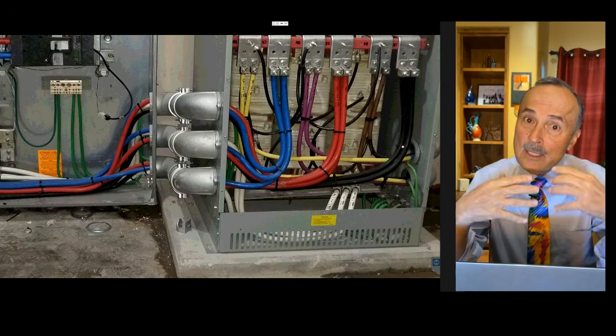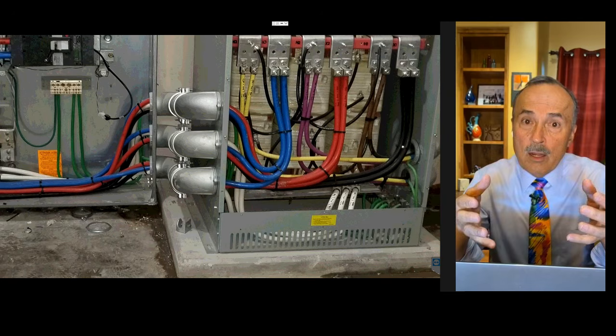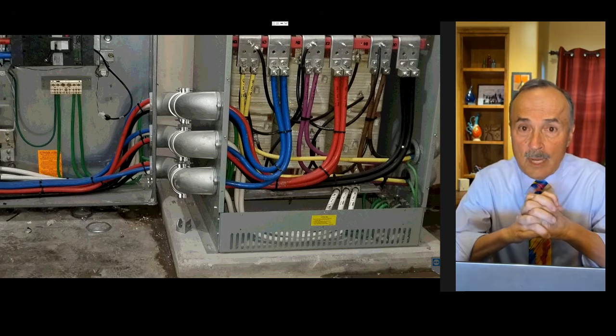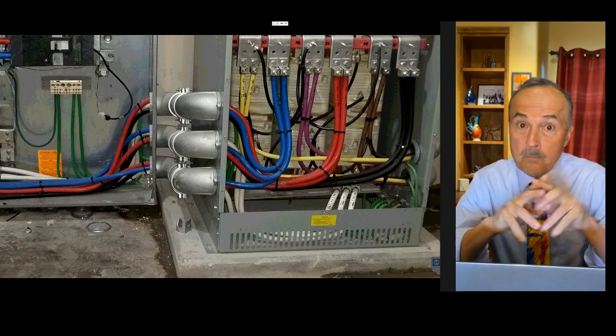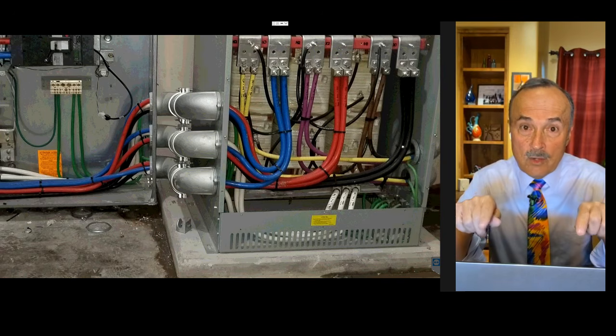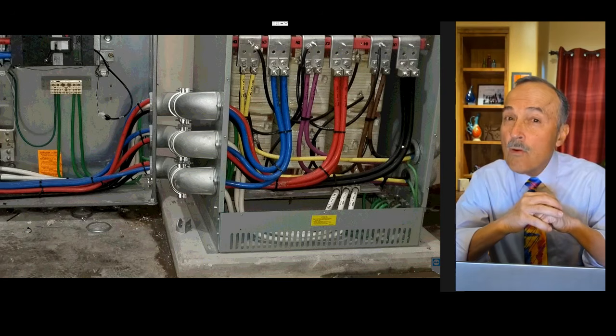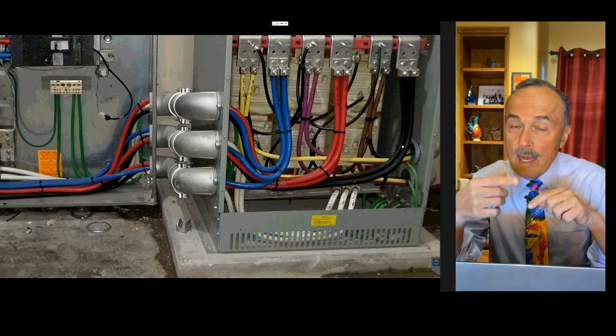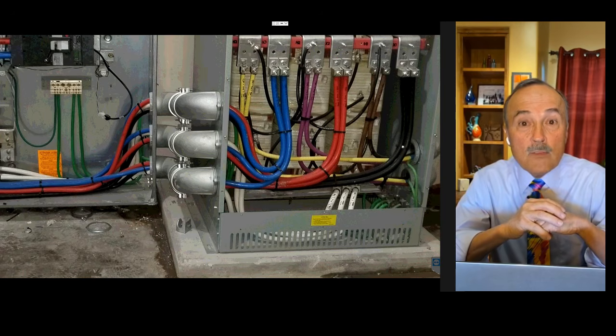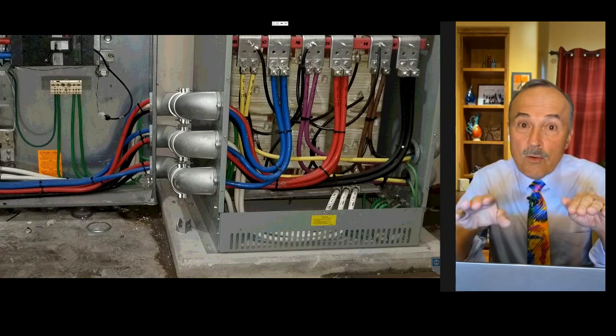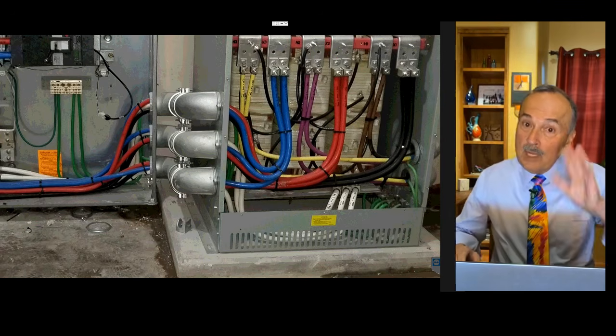And I'm trying to get the world to understand what the requirements are. There are requirements for bonding bushings and bonding jumpers, but not on the primary or the secondary of a transformer for the raceway system. So if you're at Local 3, talk to those guys out there, and if they think I'm wrong, I'm going to be here every night for a while. We'll be doing this for the next few weeks. Have them give you a code rule. Get it out of the program because you're making people confused. But I love Local 3.